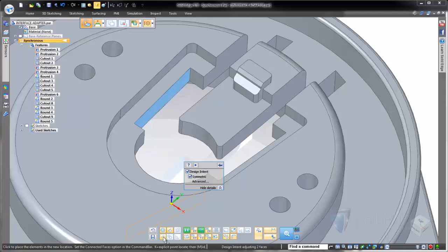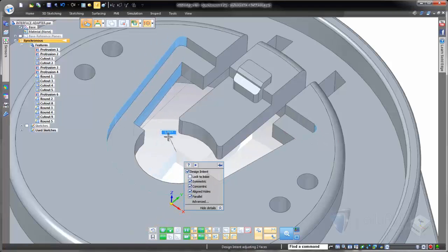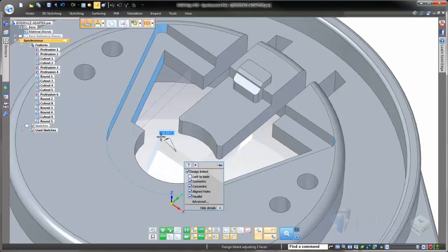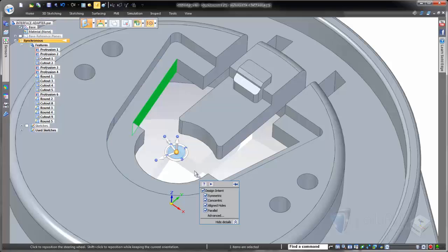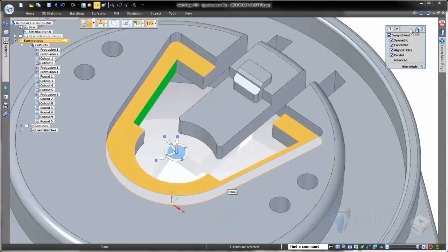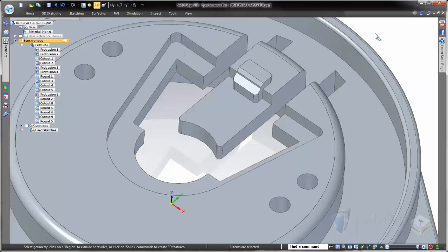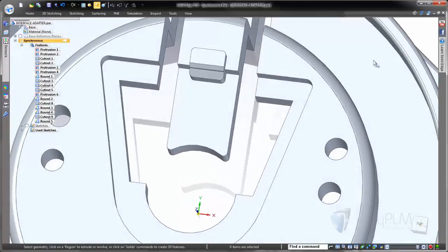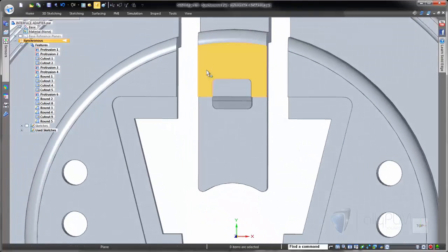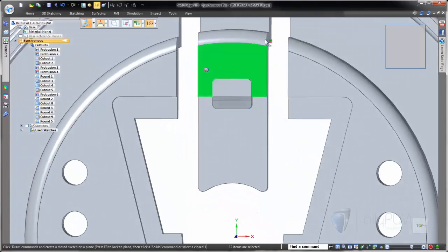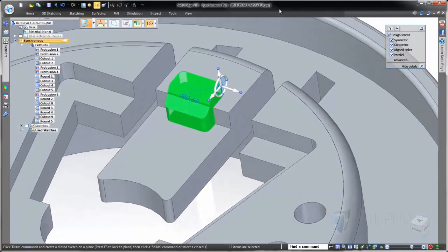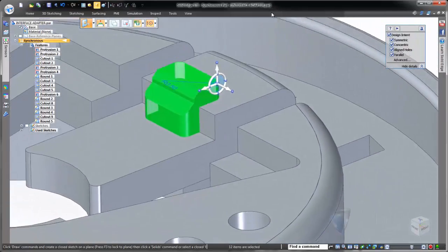In this particular area, there's another face that is parallel to the step above. In Solid Edge ST8, you can anytime invoke an advanced design intent interface where you can enable other relationships that are not turned on by default. Also, moving the design intent panel will automatically pin it to wherever you drag it in the new graphics window, and it will stay there until unpinned or moved again.